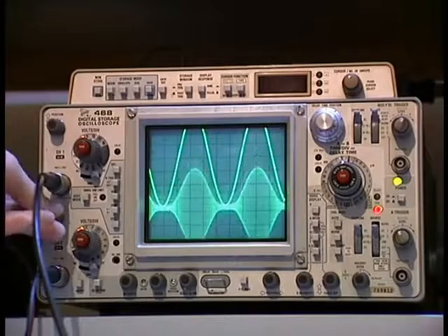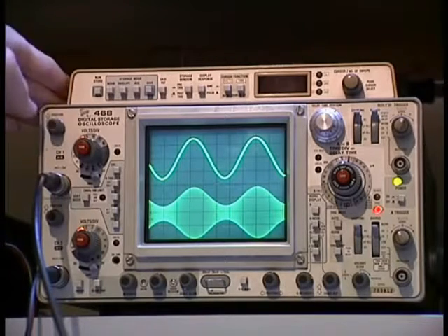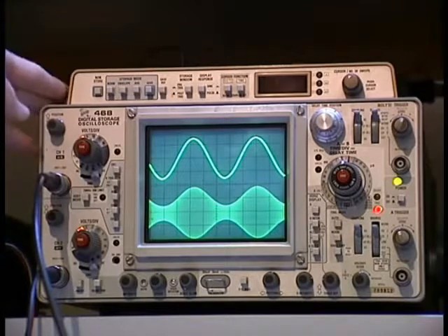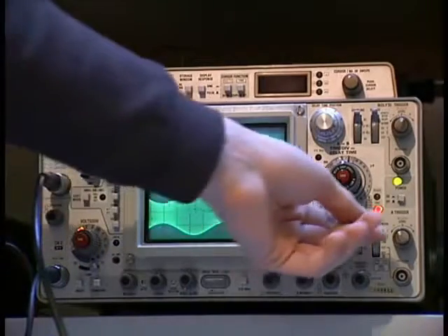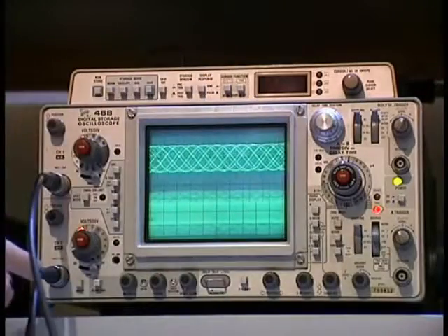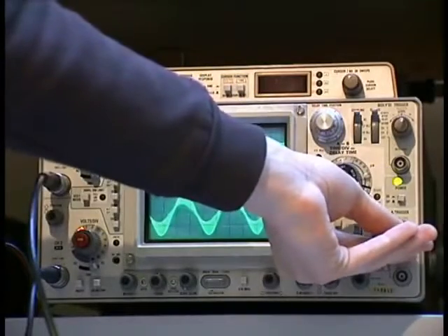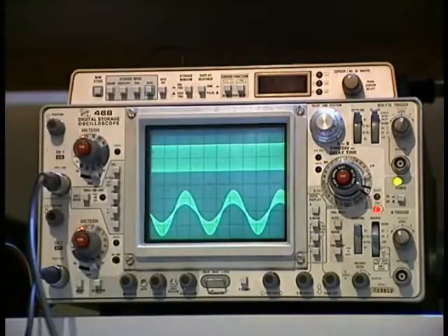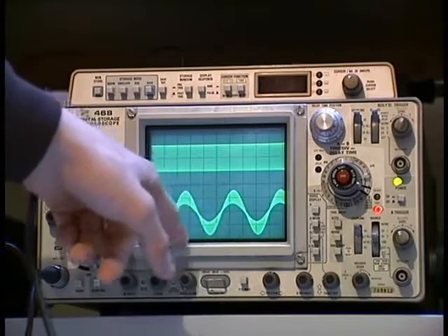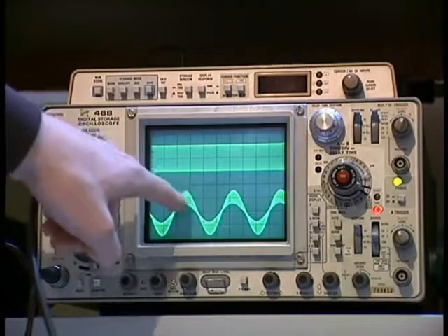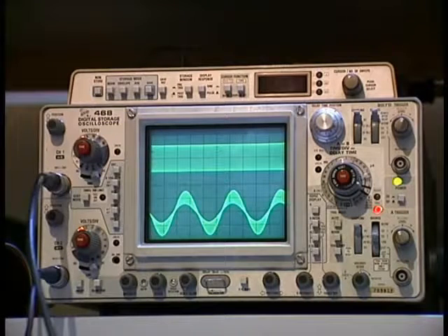In radio broadcast use, a modulation factor of about 80%, maximum 80%, is normal, but not more than 80%. Now I trigger to the second channel, to my HF signal, and put this up here, and now you can see how it looks if we look at the HF signal, triggered to the HF signal and zoomed in. You can see this is the signal, and it goes up and down with our function generator frequency.